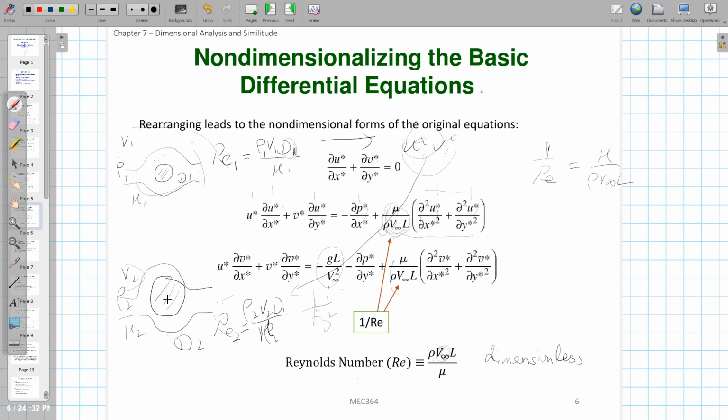So in these cases, we see that these two problems are similar. Their flow fields will be similar, just a scaling of the same result with different parameters. This result is just a scaling of that one, obtained by multiplying by a reference velocity, pressure, or whatever constant reference value, because their non-dimensional results are the same.